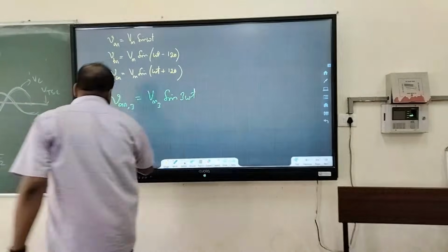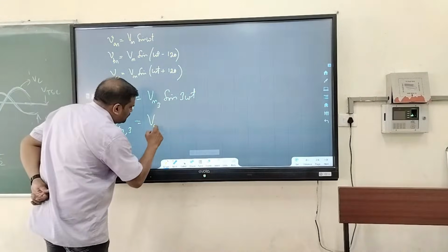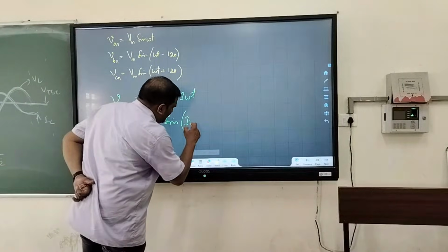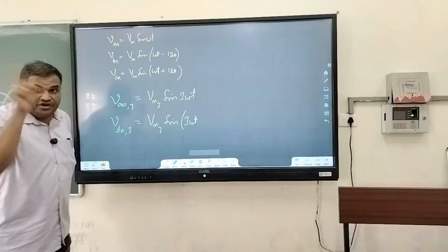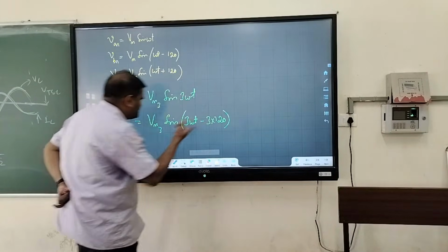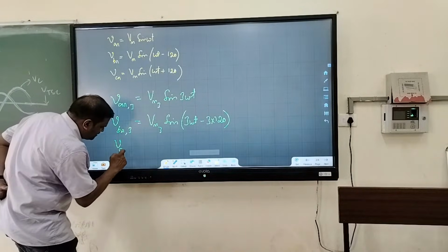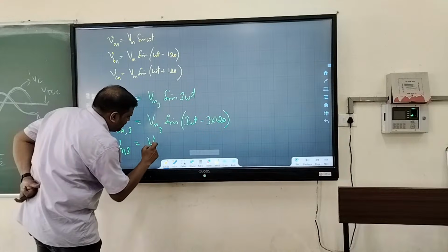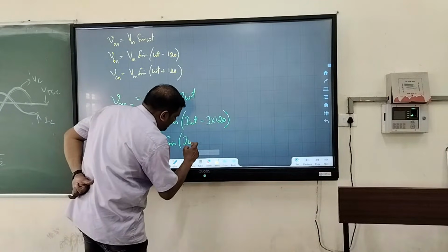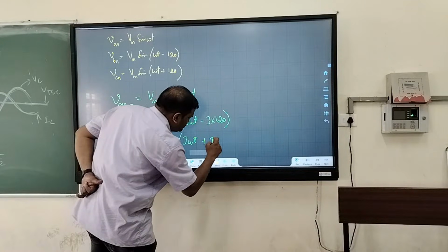What is VBN? VBN third harmonic will be equal to VM3 sine of 3 omega t minus 3 times 120. This is VBN3. What is VCN3? VCN3 is VM3 sine of 3 omega t plus 120, so I can write plus 3 into 120.